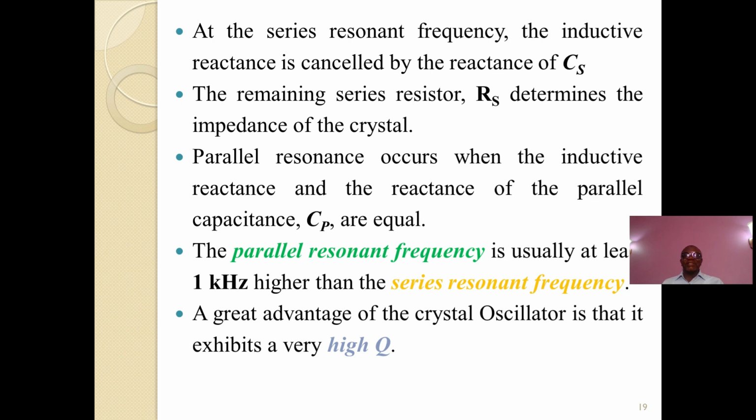The remaining series resistor RS determines the impedance of the crystal. And parallel resonance occurs when the inductive reactance and the reactance of the parallel capacitance CP are equal. I'm sure that my listeners must have treated resonances in their basic electric circuit theory.